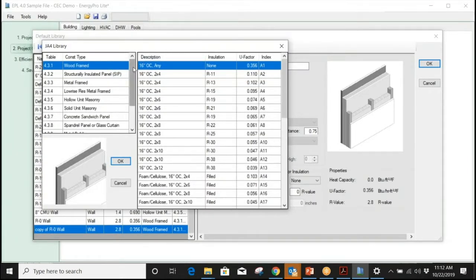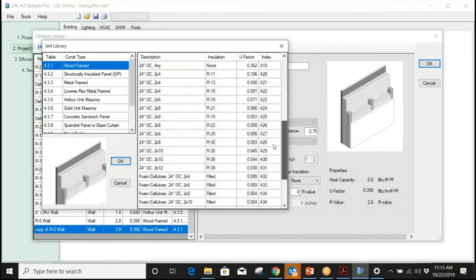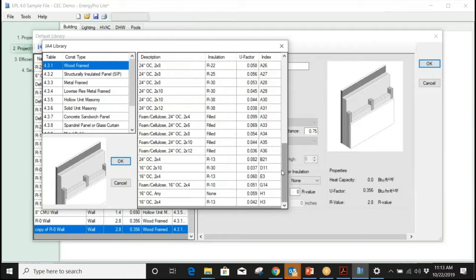And generally, if you're in a concrete building, you can go to a unit or a window that's in a common area in that building, get in and look down and see, use a ruler or a tape measure and figure out what the thickness of that wall is, where the window is, because you can have access to see where it ends on the outside, where it ends on the inside, maybe subtract the amount of drywall or exterior siding that it has.